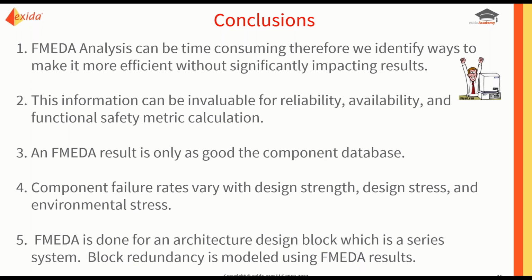Component failure rates vary with design strength and environmental stress, and with the ability to change these within the tool, you're able to see this instantly as the results update. And then FMEDA is done for an architecture design block, which is a series system. Block redundancy is modeled using FMEDA results.